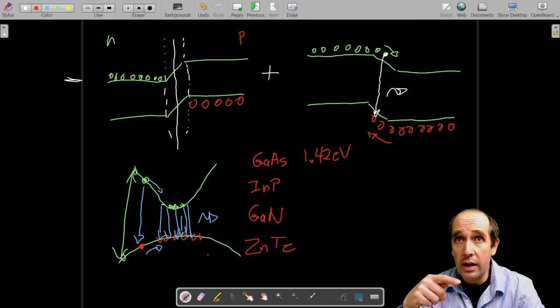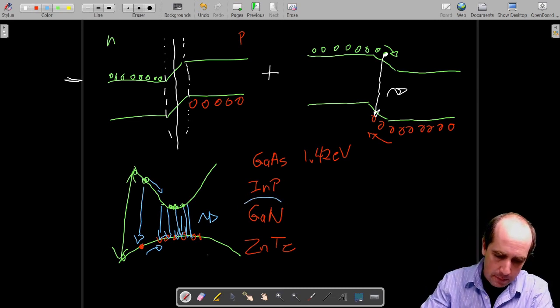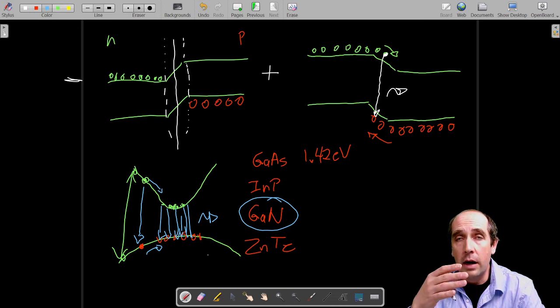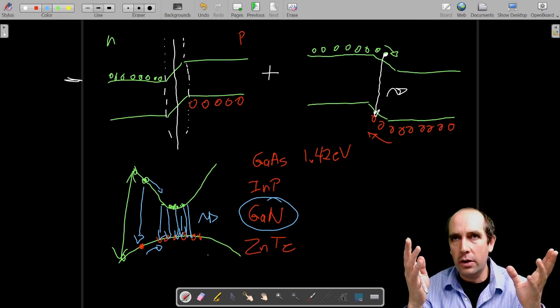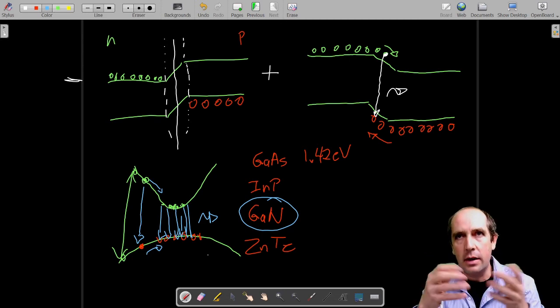The way they work, they are actually gallium nitride blue LEDs, coated with a material that absorbs blue photons and then re-emits in many colors. So in a sense, a white LED is really a blue LED with a fluorescent coating.